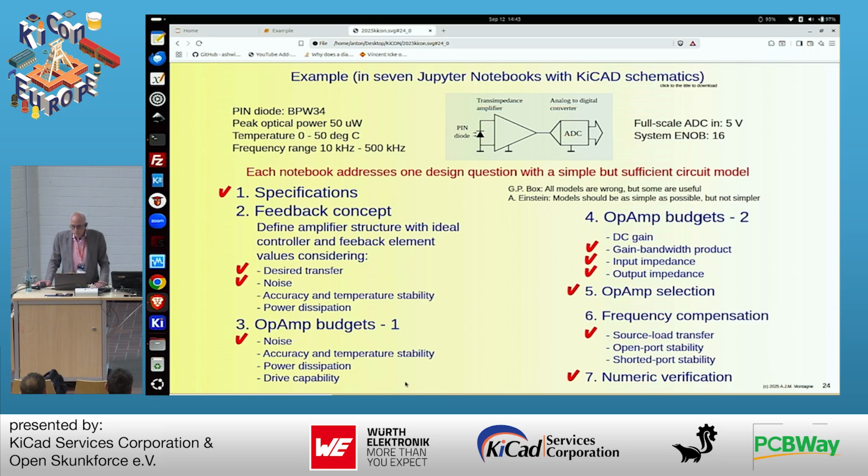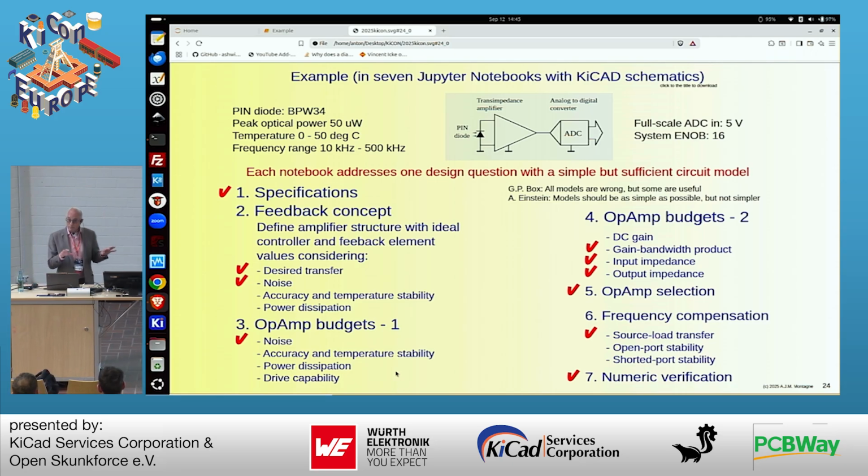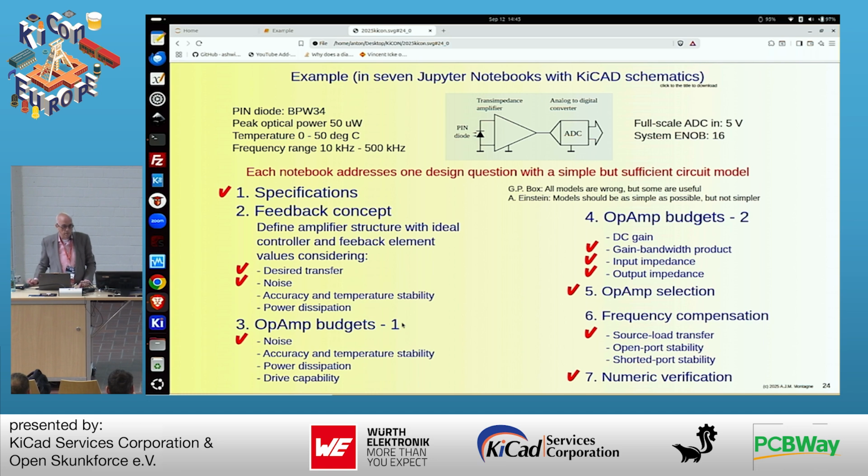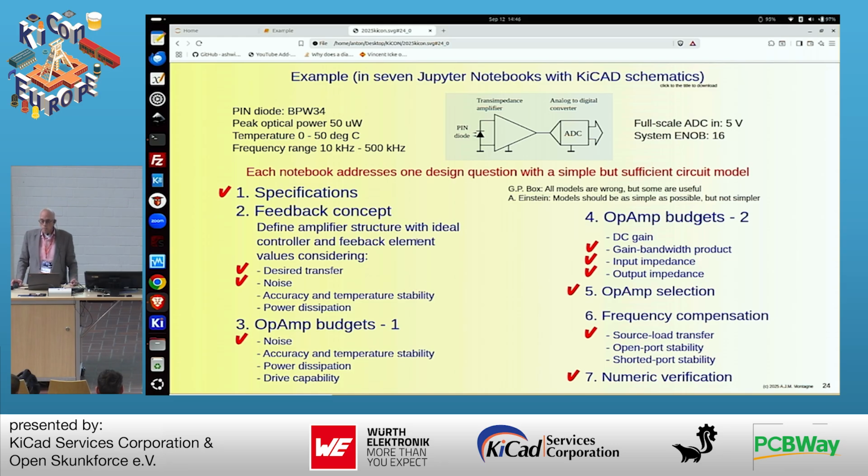Design is risk management. Basically, the process of designing is like the biggest risk first. Let's say we want to make this airplane and everything fits, and the last screw in the wheel doesn't fit, then it doesn't fly. And that's a waste. It's always the devil is in the details, in the last details. So we have to be sure that we address that. That is called top-down design with bottom-up awareness. You need to know your technology, otherwise you cannot do it. And you need to know about showstoppers.